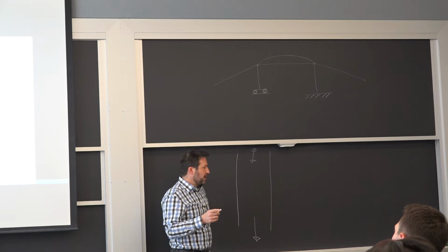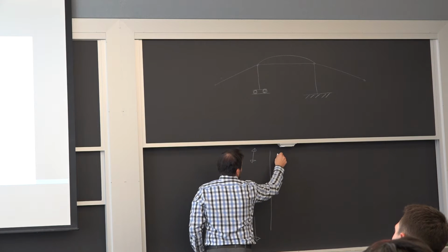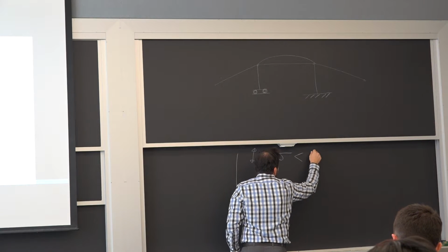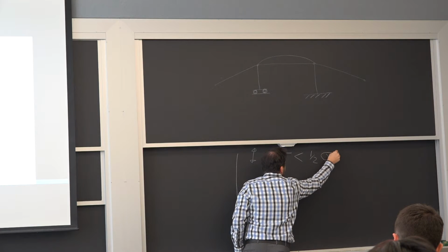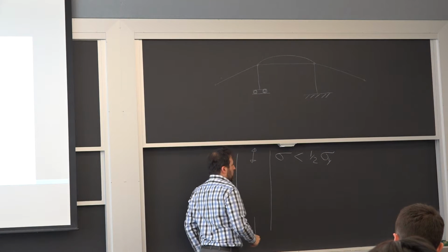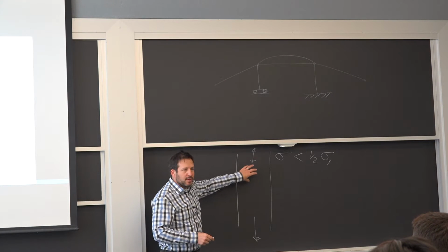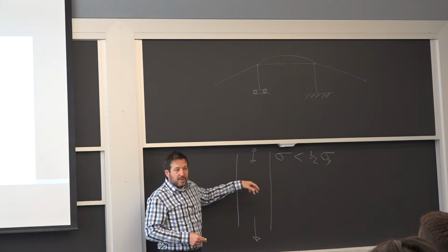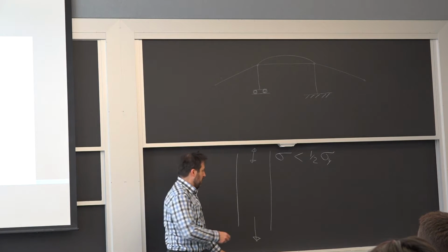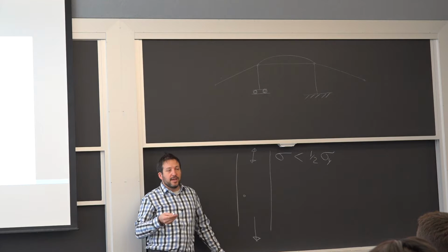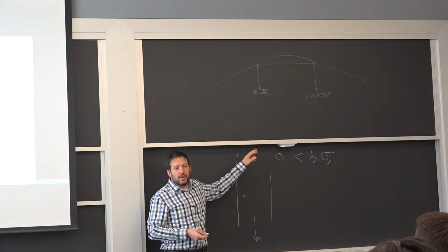What happens is if this stress is significantly less than, let's say, half the yield strength, the way I'd like you to think of it is locally in this material, there will be inclusions, there'll be some anomalies, and around the anomaly you do have a stress concentration. You have extra loads that are not part of your nominal load.